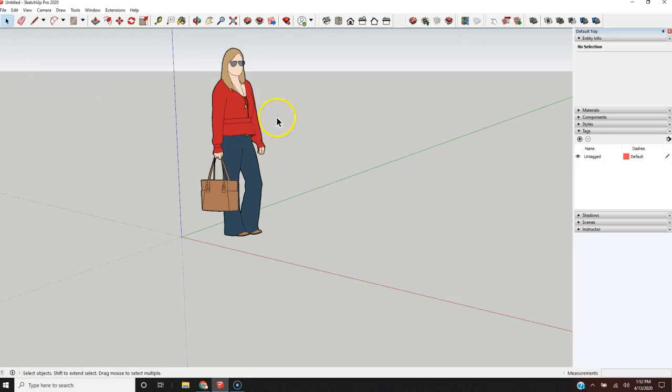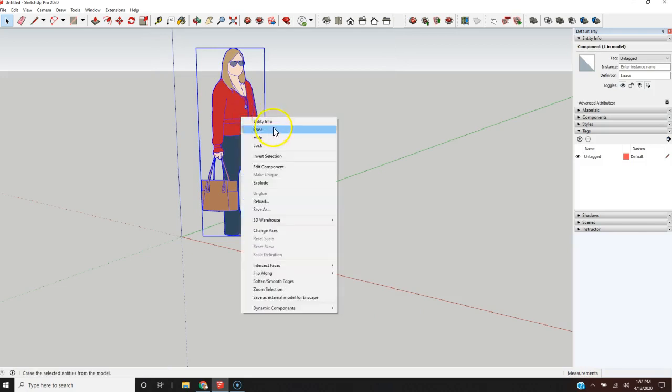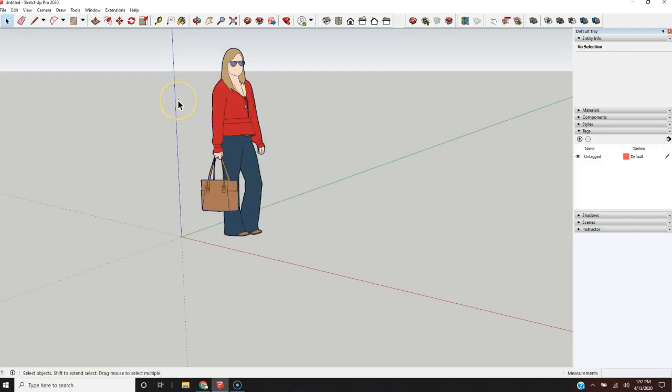familiar with them. And so right now, this arrow that you see as my cursor, this is the select command. If I left click and hold, I can select anything in SketchUp. And I selected this lady, and that's that command. It's a very useful command in selecting lines and manipulating things and editing things. If you hit the space bar, you automatically get into the select command.